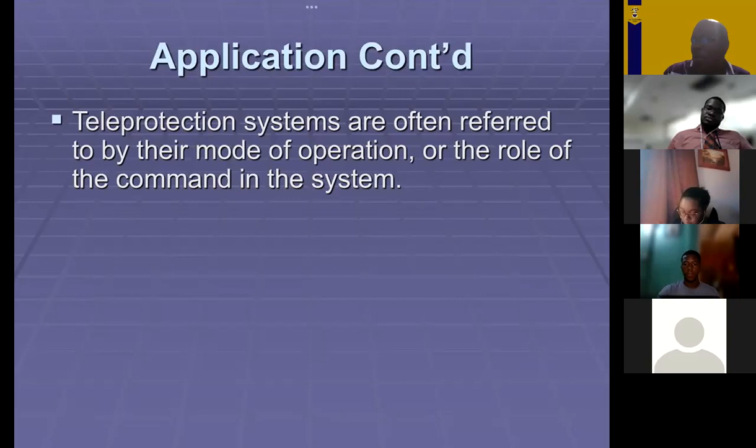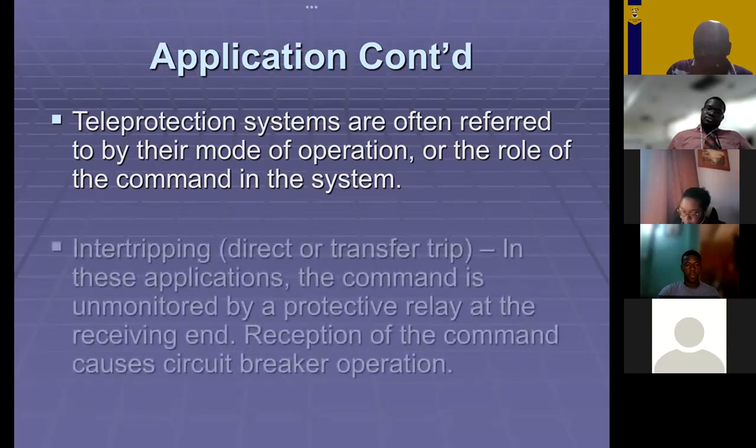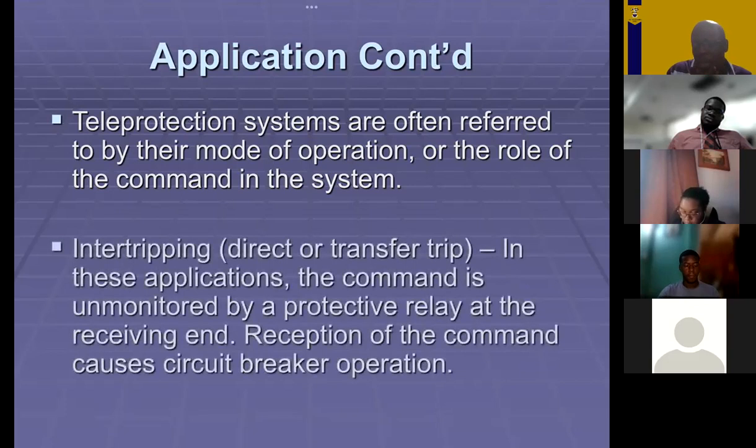So the teleprotection systems are often referred to by their mode of operation. And we went through this. I know I introduced them to you last week without getting into this. So we talk about your inter-tripping or your direct or transfer tripping. And this is where you're going to trip simply because you received the signal. So there's no monitoring.